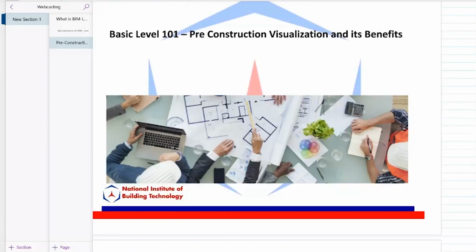Every time someone came with a question, I would open this 3D model and say, listen, this is the door, see how you go through here and put this door here. I would cut a section. He said, I don't know how to do this. I'll just take the model and cut a section at that location. It was so interactive, because in a CAD world, the section is the section. What you get is what you get. If you have to create a section where there is no section, it takes a lot of time. In the information model, it's a matter of 5 minutes. You can take sections anywhere. You can make 3D models of anything in 5 to 10 minutes because you already have a full model. It's just a matter of selectively taking the information out.